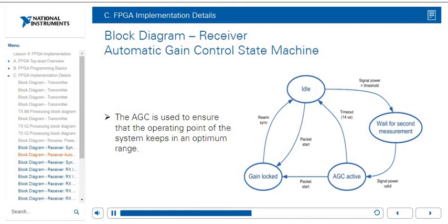This second value will be used to determine the applied gain for the current packet based on a host configurable mapping table. In the current implementation, the AGC is able to apply 4 different gain levels: 0 dB, 10.5 dB, 21 dB, or the maximum value of 31.5 dB.